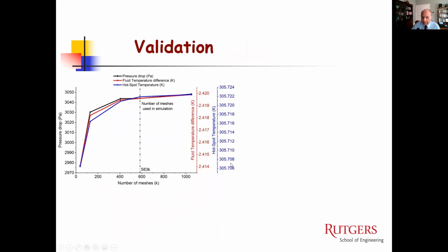So we did that, using fairly standard computational heat transfer procedures for channel flow. And we find that the results are reasonable. Some validation was done with respect to some results here. As you can see here, the first part is only to show that the mesh is chosen so that further reduction in the mesh size would not affect the solution.